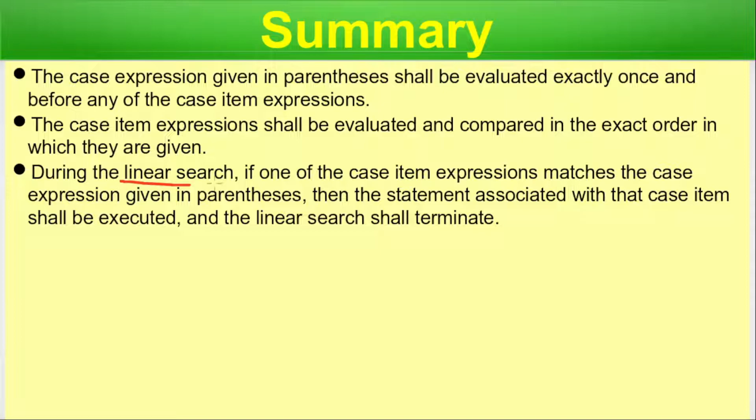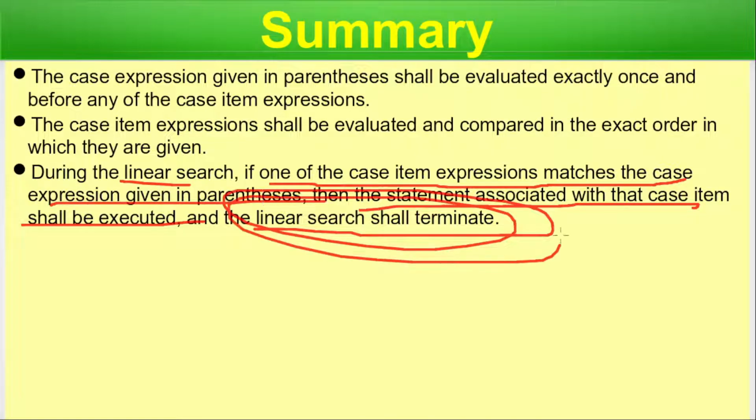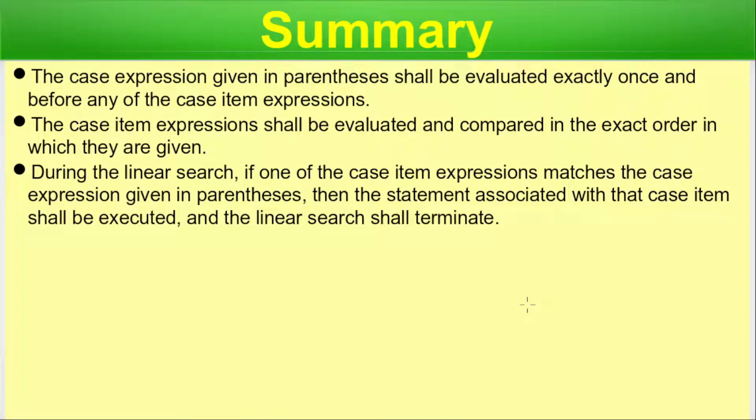During the linear search, if one of the case item expressions matches the case expression given in the parenthesis, then the statement associated with that case shall be executed and the linear search should terminate. So this is the most important point. Once you have a match, it goes out of the case statement. By executing the lookup table expression, it goes out of the case statement. It does not search any further.